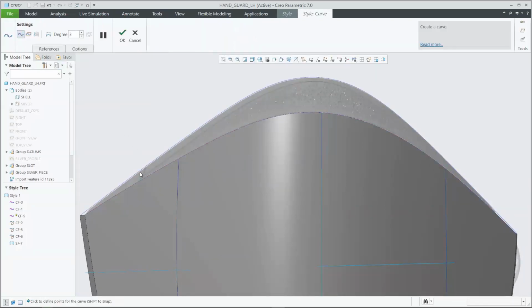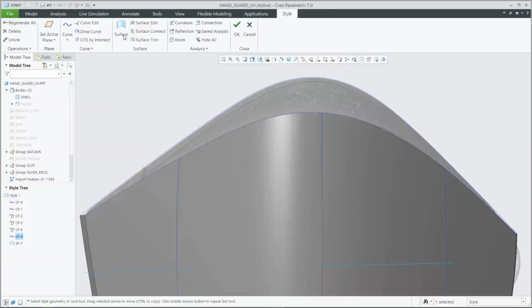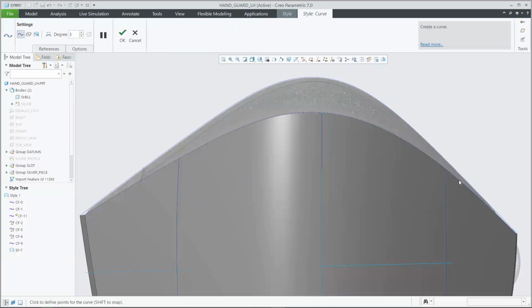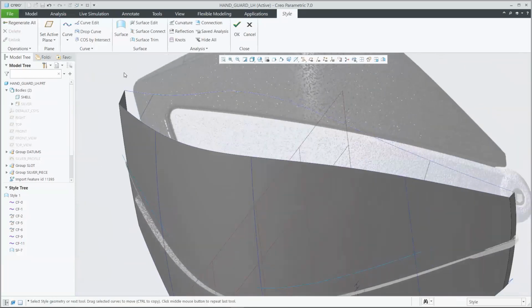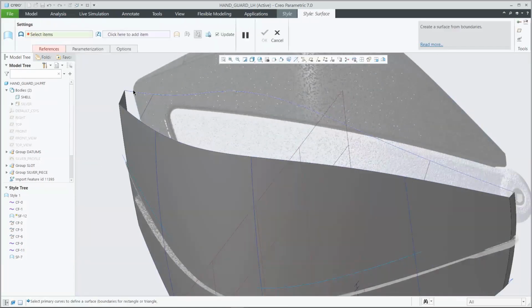We're good to go, keep moving along to some of the top sections and the bottom as well. Now, the first thing that I'll need to do is add in a couple of 3D free curves here along some of our existing curves. It's just going to make sure that the surfaces that we're adding in here up at the top are going to transition well into the surfaces that we already built out. And with these ones here, we'll go ahead and select on the 4 bounding curves along the outside region that we want to place that curve in.